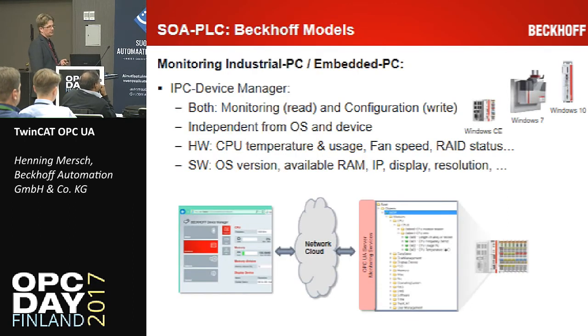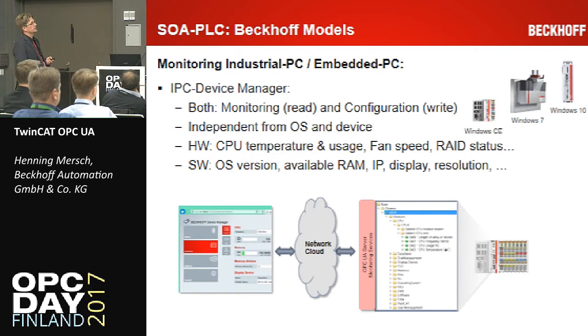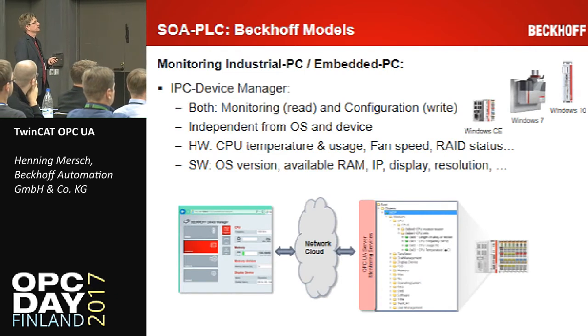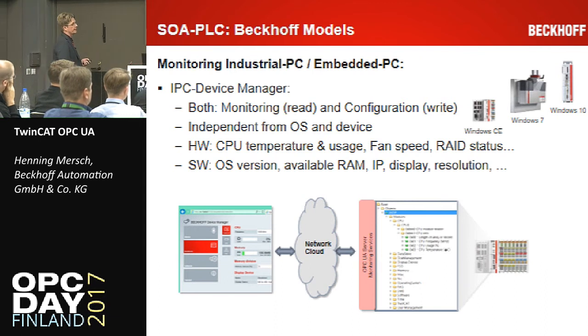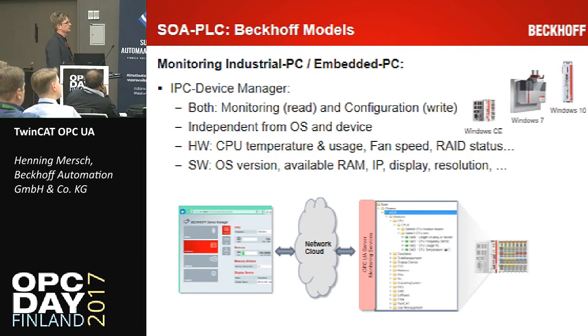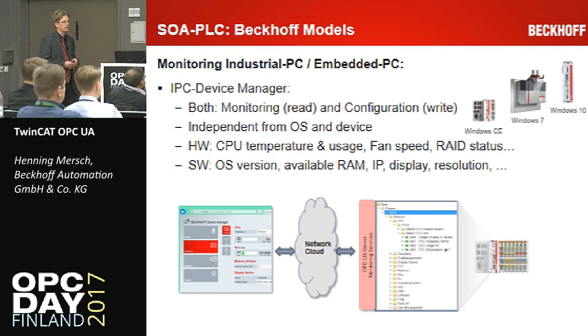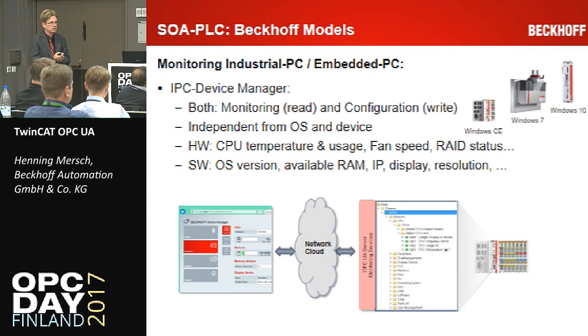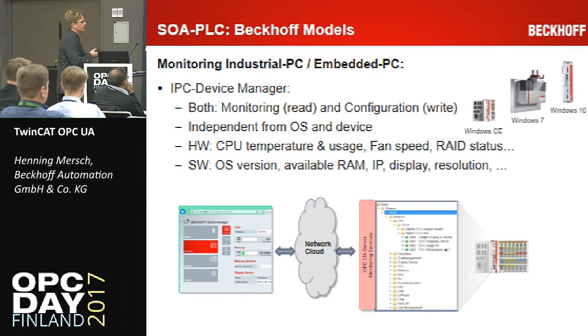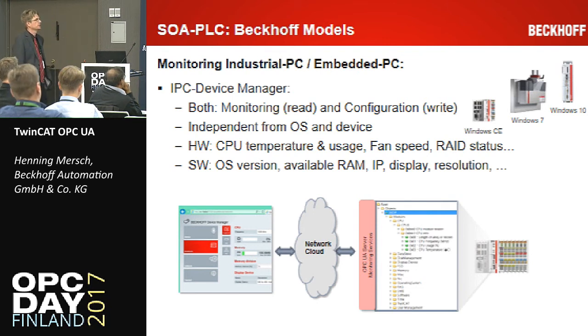The Beckhoff world has another one or two models currently that we are providing. The first one is the IPC device manager UA interface, where you have access to the heat of the CPU, to the load of the CPU, of the memory, and so on. There simply is no companion specification for that, so we need to invent our own there. And it's partly used by our customers. They are happy with that, but sometimes maybe some CPU vendor would define such a companion specification, and then we could additionally support that.